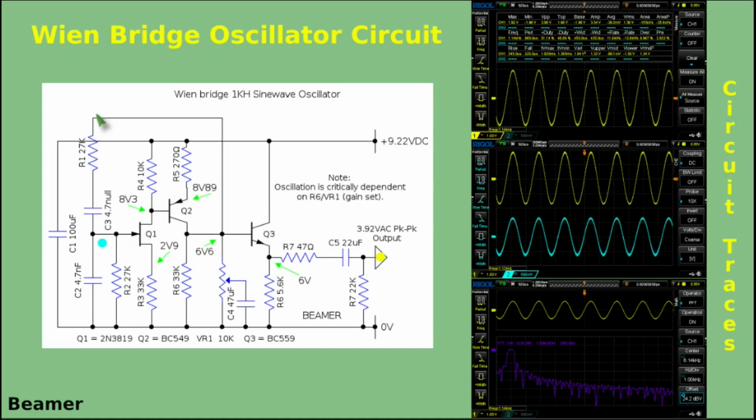But we've got a drop in voltage here between those 2 points. To make up for that drop, you need to have this little amplifier not only 360 degrees, 0 degrees, equivalent to, it has to have a gain of a minimum of 3 to make up for that loss. And in fact, usually Wien Bridge oscillators would like something in the order of 3.1 gain. So you need just a little bit above the loss made up in this network to make the circuit oscillate.